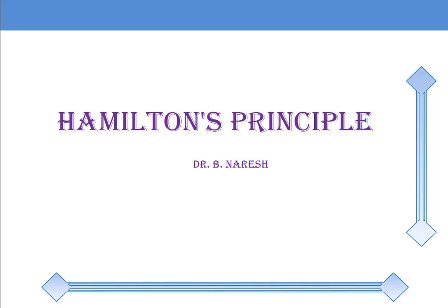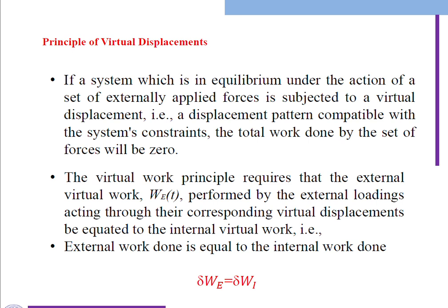So I am moving to work done. That is nothing but virtual work done in your body. So we will see the principle of virtual displacement. What is the virtual displacement? If a system which is in equilibrium under the action of a set of externally applied forces is subjected to virtual displacement, that is nothing but a displacement pattern compatible with the system's constraints, the total work done by the set of forces will be zero.